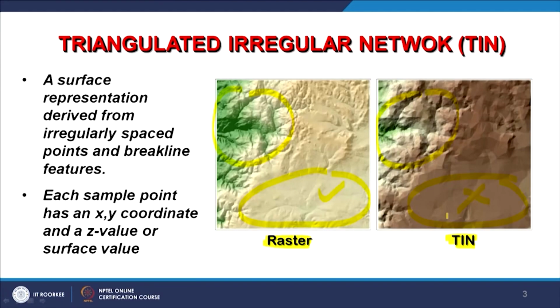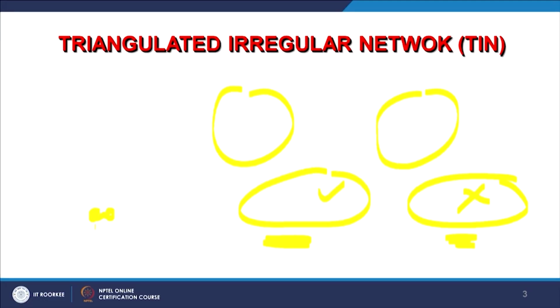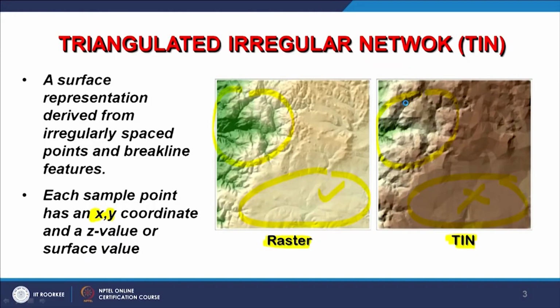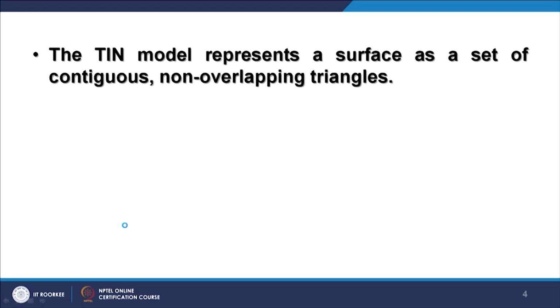Of course, here also when we provide the data for generation of TIN, three things are very much required, essential. One is the x coordinate, y coordinate, so it is a pair, maybe many points. Like here when I was showing that these are the points, and for these points one more value you have to provide, and that can be the elevation value, that is the Z value. So, the Z value is also provided here to create the surface, whether TIN or raster.